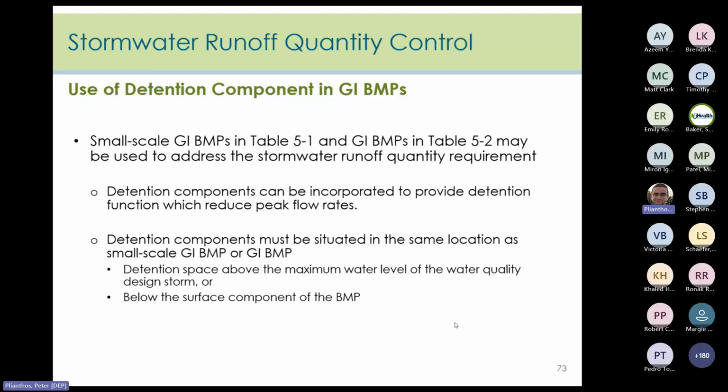The important part is that the detention components must be situated in the same location as the BMP, either above the water quality design storm elevation or below the surface. A BMP with a detention component located downstream, outside of the basin's footprint, does not meet the design requirements as stated in the BMP manual.